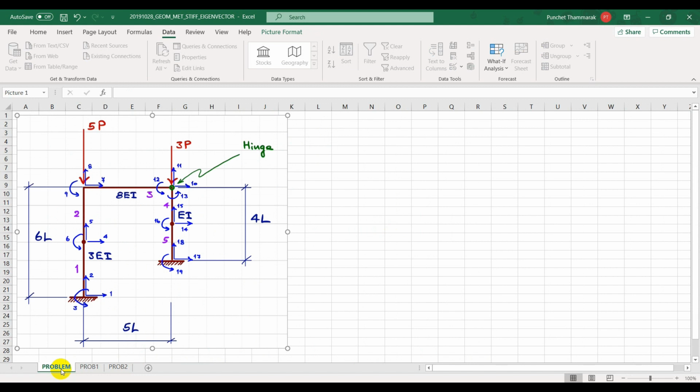Well, the left column has some advantage in that the rotation is also restrained, whereas the right column does not have any restraint in rotation, but it has a restraining effect on the left column in the, well, how to say, horizontal displacement restraining.